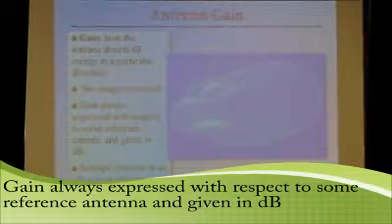That's why having a rotatable array works very well, and having something that you can focus your beam. Typically you want to focus on the short path, but if you find out a long path is working, you turn it around and go the other way. Anyway, having a beam or directional antenna allows you to focus your signal in whatever direction gives you the best chance to talk to where you're trying to talk to. So that's why directional antennas are so highly desired, is that they do that.